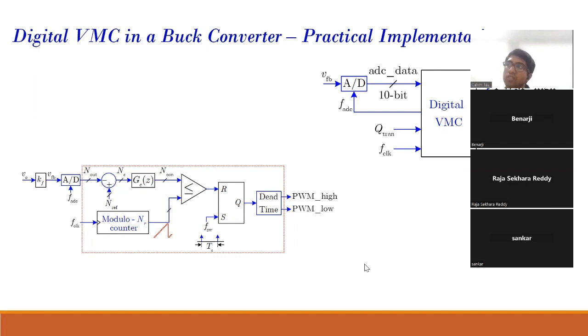If the reset is non-zero, if the reset is 1, then the counter will go to 0, no? If the reset becomes 1, the counter will go to 0. If it is not equal to 1, then the counter will either hold its previous state, or when the clock comes, it will get incremented.